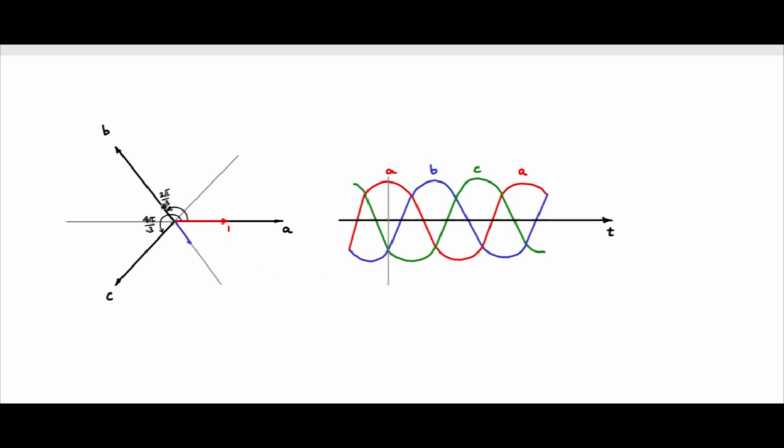Now I will put, say, negative 0.5. So B phase axis is here, negative 0.5 is here, and C phase axis is here, negative C phase axis is on that side. So I will say C 0.5. Now these two contribute to the overall resultant vector. This is 60 degrees, this is 60 degrees, cos 60 is 0.5.